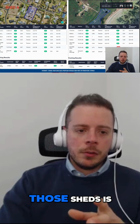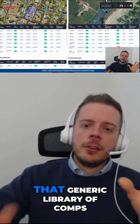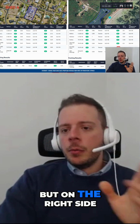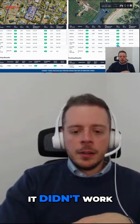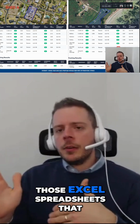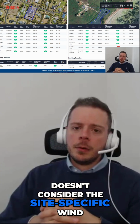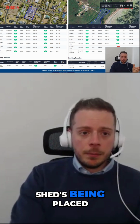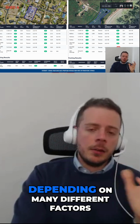So the outcome for those sheds is, if I was using that generic library of computations, it worked on the left side, but on the right side, on shed B, it didn't work. I just want to bring that up so you can see that if you're using those Excel spreadsheets that don't consider the site-specific wind, you might be doing something wrong depending on where that shed's being placed, and depending on the orientation, depending on many different factors.